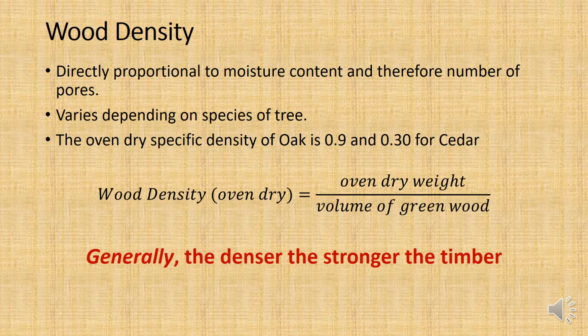Now, the other thing which really influences the porosity of the wood and the amount of moisture content a wood can hold is the density of the wood. Now, we tend to measure density, like many materials, by specific density or specific gravity. So it's basically a ratio of the wood's density to the density of water.